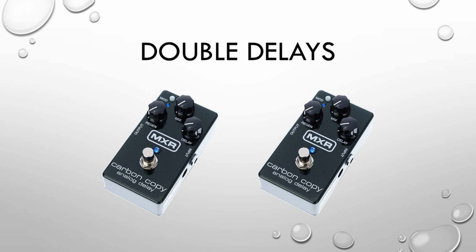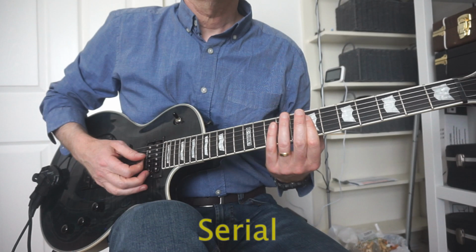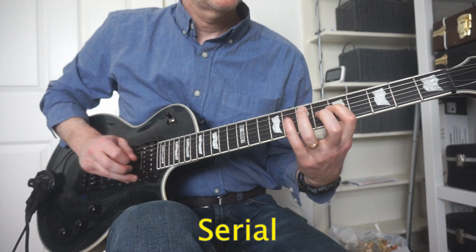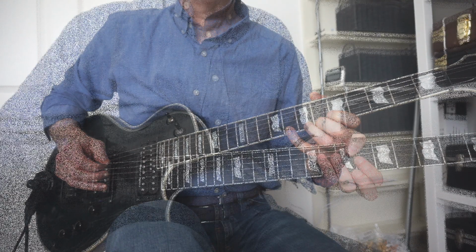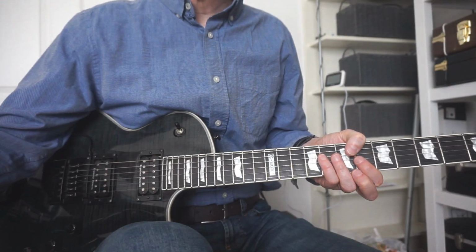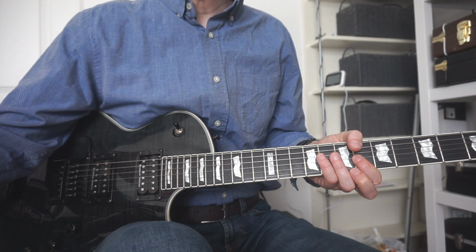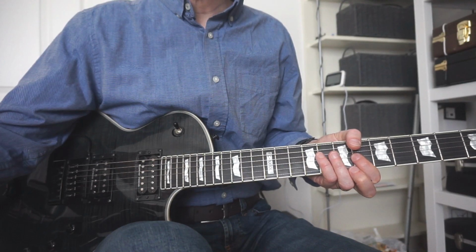Firstly, if you're running two delays, one short and one long for example, running them as serial means that the repeats of the first will also be repeated by the second alongside the original signal. Now you may actually want this, and it does have its applications, but generally it will create a lot of unwanted repeats. Running the two delays in parallel will eliminate this.